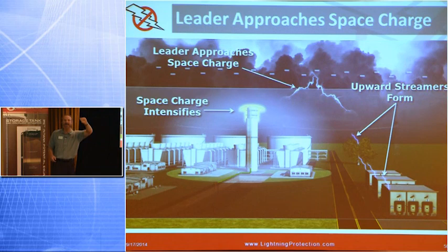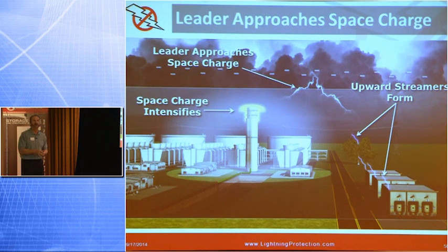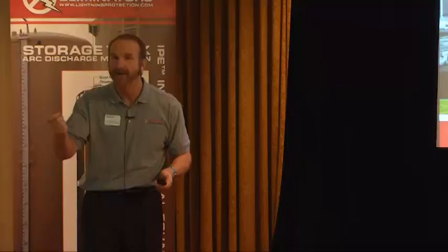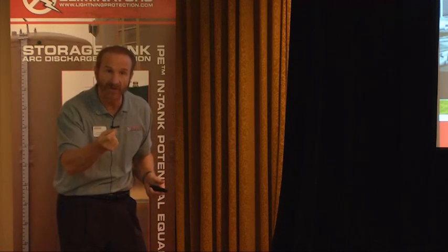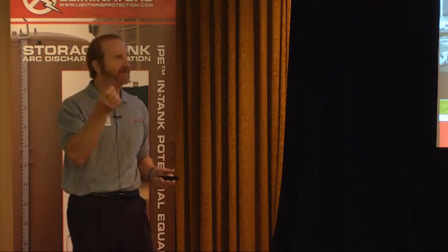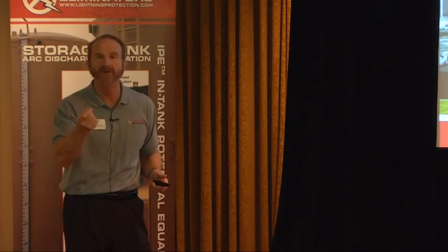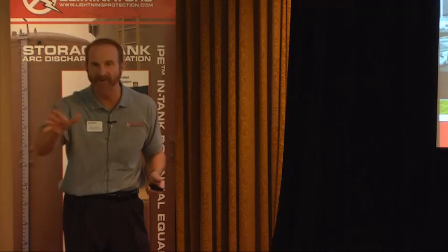We don't care if that lightning leader is 100 meters away or a mile away. We just want to make sure of two things we don't want. We don't want that branch to get into my area to where I develop an upward streamer. We know that we have to have an upward streamer to win collection. And in order to develop an upward streamer, the electrostatic field potential, which I don't think I touched base on, very important, has to be 100,000 volts a meter, approximately.